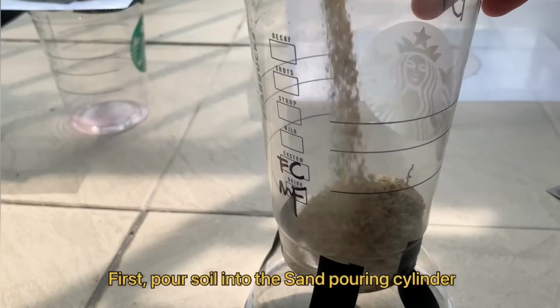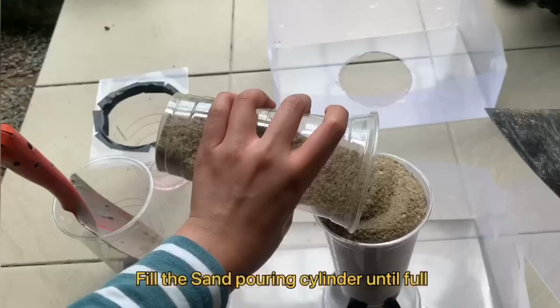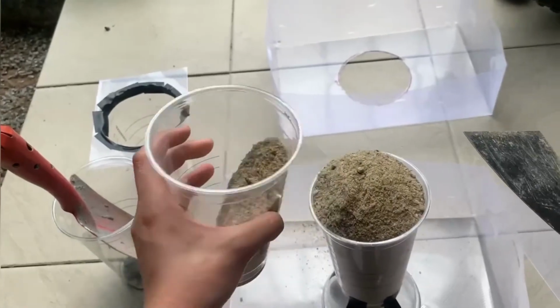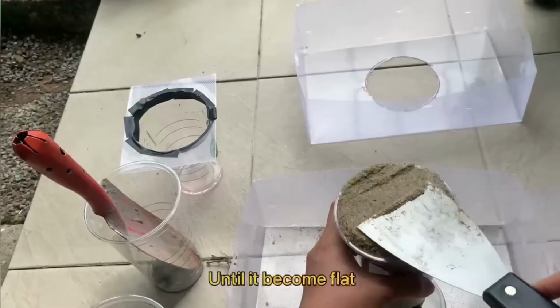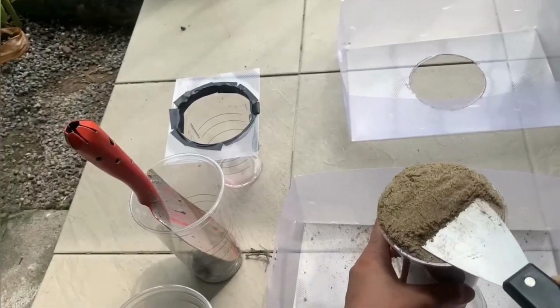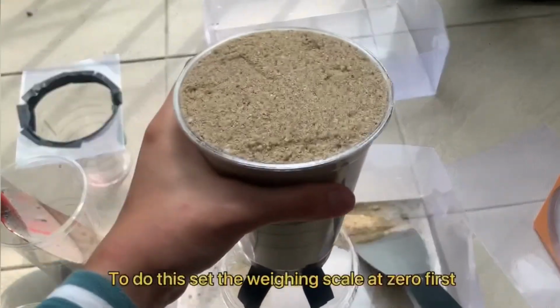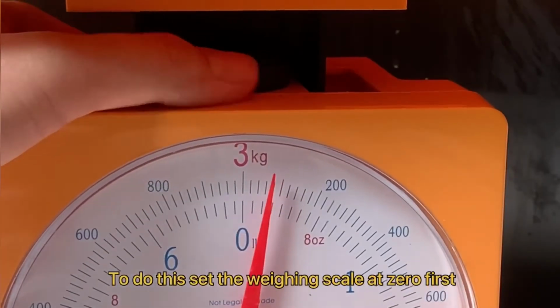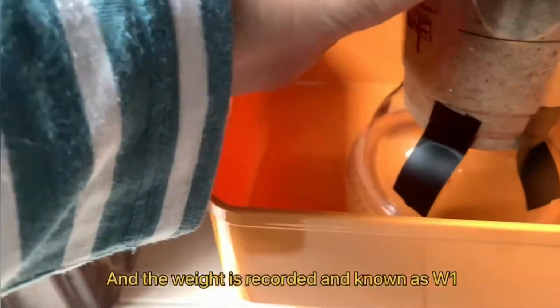First, pour sand into the sand pouring cylinder. Fill the sand pouring cylinder until full. By using the scraper, spread the sand evenly until it becomes flat. Next, weigh the mass by using the weighing scale. To do this, set the weighing scale at 0 first, and the weight is recorded and known as W1.